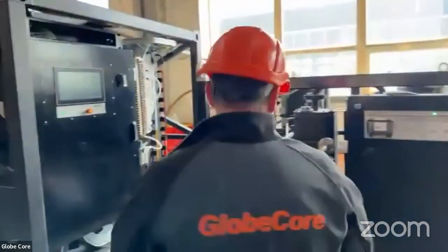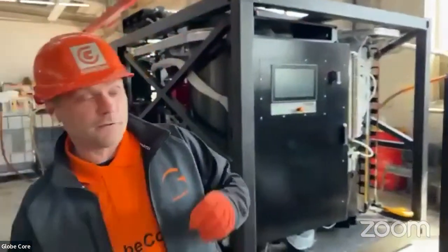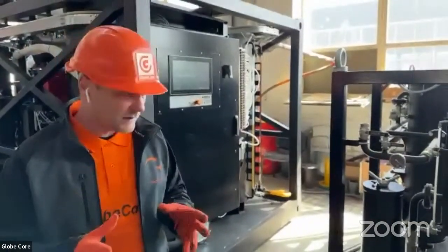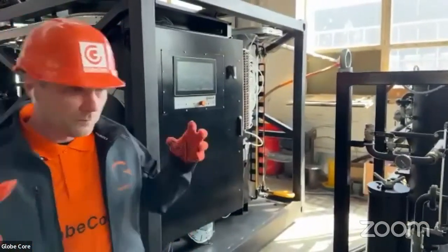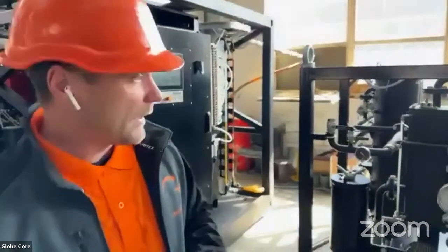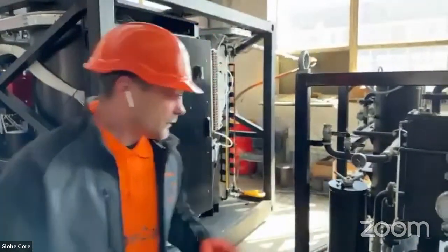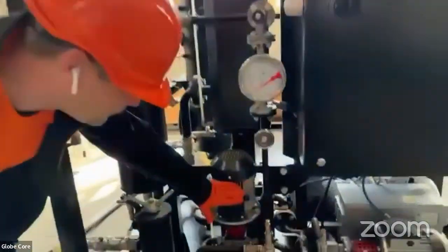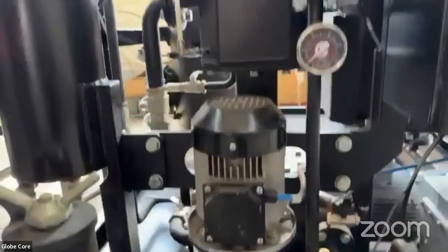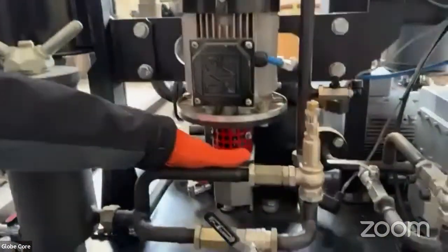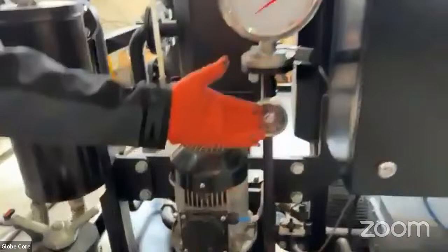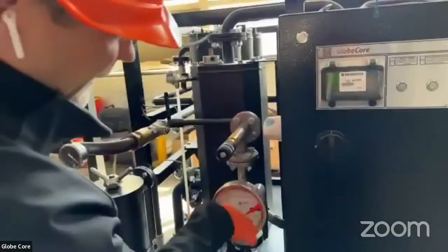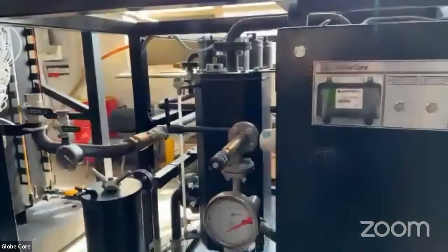Okay, so in fact, the regeneration process is implemented in a very simple way. We just need to put the oil and the sorbent into interaction. To do this, we just push oil with the inlet pump into the columns. We use a gear pump here, a manometer, a flow meter, and an adjusting valve to adjust the capacity of the process.